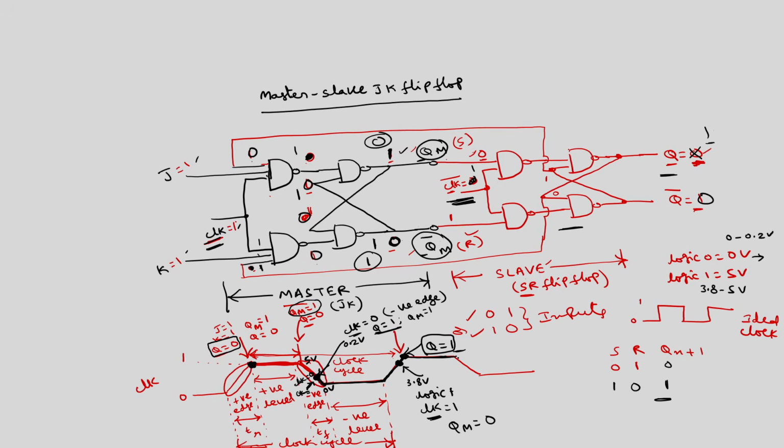This particular flip flop is called a negative edge triggered flip flop. Now, race around is not there because throughout this one clock cycle, from here to here, the output has changed only once at this point. Okay. So in that way we can avoid the race around condition.